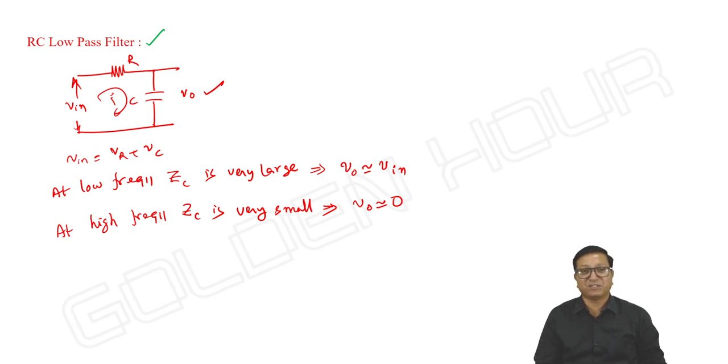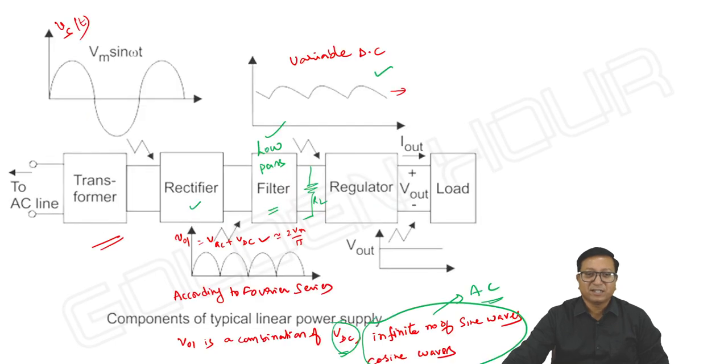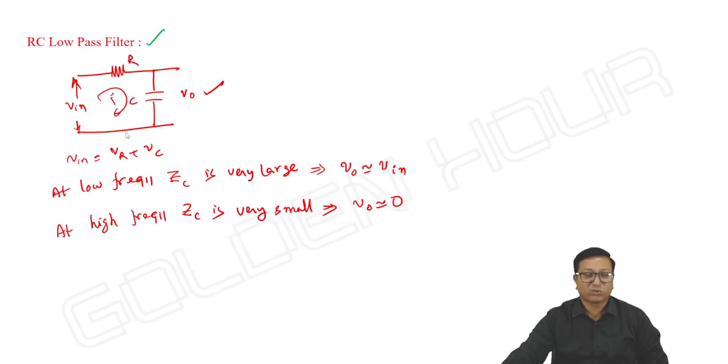If the input frequency is high, that appears with more attenuation at the output. That's a simple principle, right? So now that's what we are doing here. If any high frequency signal component is present at this point, that is not appearing after the filter, and any low frequency component comes, that is sent to the load resistor. That's the idea here. That's what is possible with this.